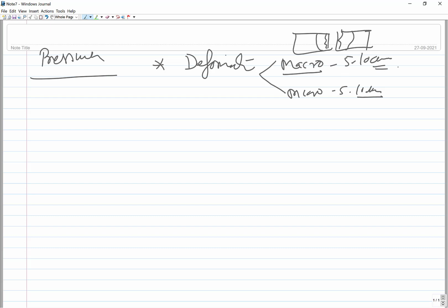Depending on the process, friction welding, friction stir welding, forge welding, and cold welding will all need a lot of deformation. But ultrasonic welding, electromagnetic pulse welding, or explosive welding will need very limited interfacial deformation for developing the joint. So one application of pressure is to facilitate the deformation.